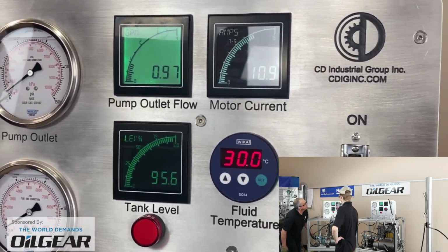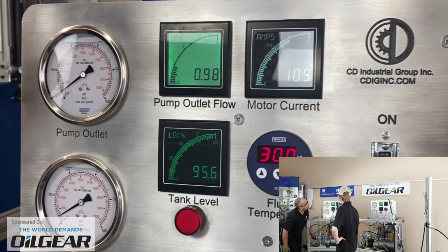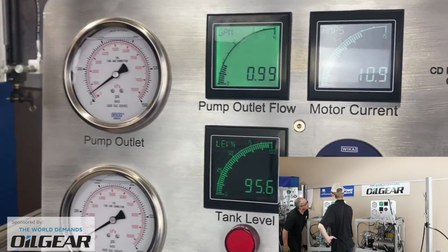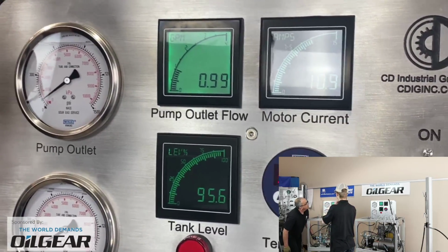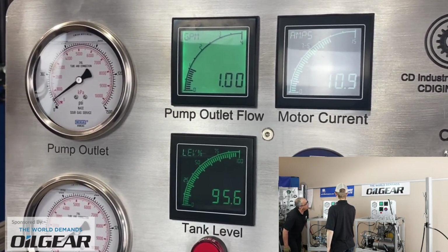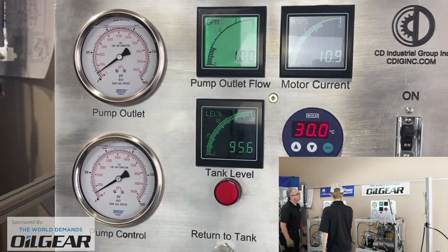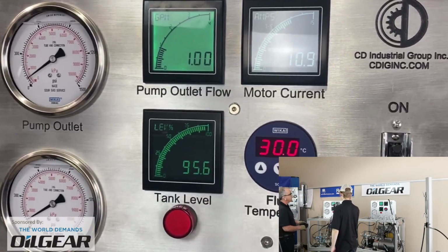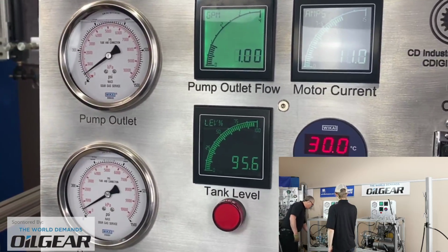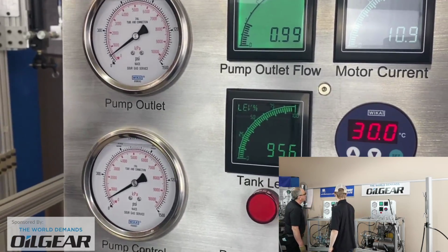And I should also mention that there may be a recommended correct temperature for your system to make these changes. I believe I mentioned temperature a moment ago and I didn't finish that, because not so much flow, perhaps a little bit flow will change, but most certainly the pressure compensate value and maximum flow rate may change a bit as you come to the normal working temperatures. And then of course you must be careful not to get burned by hot hydraulic parts.